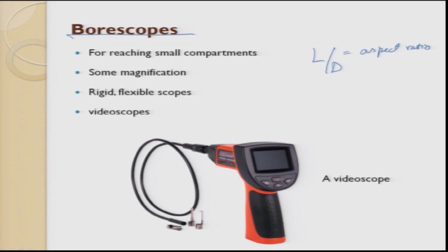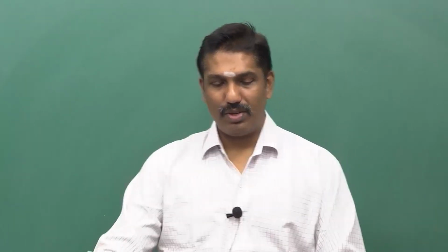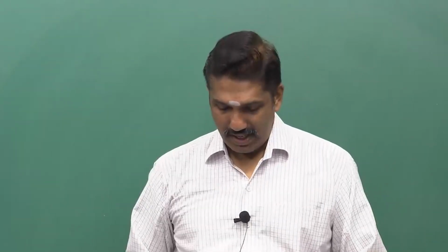In a borescope, you have a camera and a light which is thrown. This is an optical fiber, which transmits information, and through this screen you try to see what the crack within the surface is. This is used for aeroplanes, for example the blades, if you want more information on non-accessible regions from the surface. Then they use a borescope and we try to get the information.